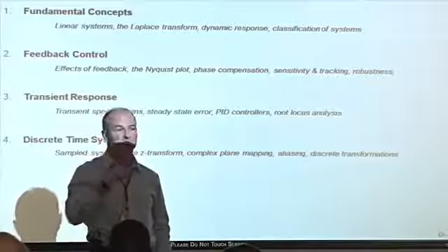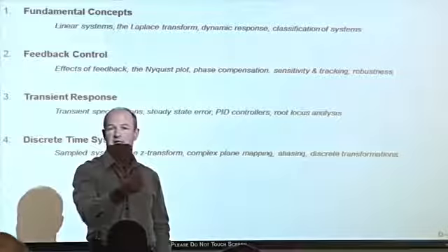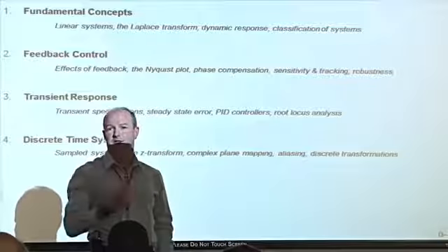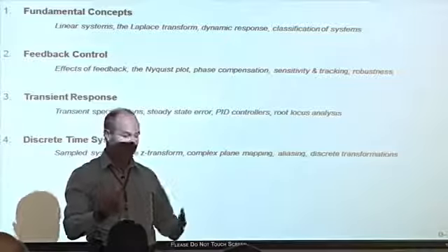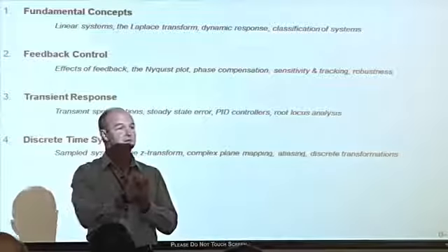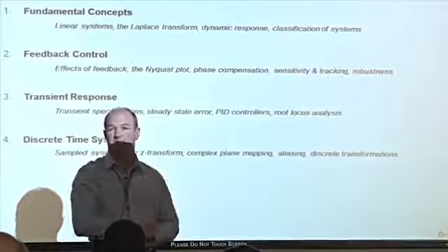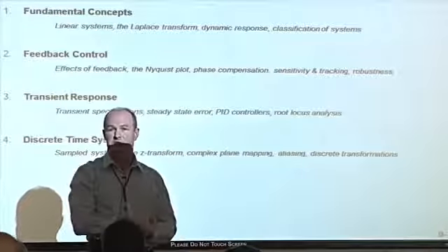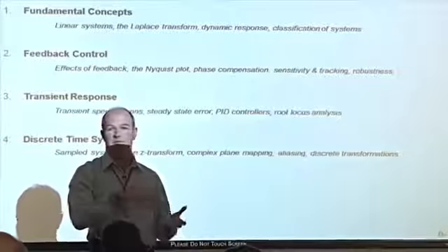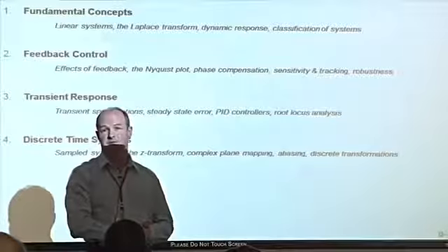You apply some kind of discontinuous input, such as a step, and then you analyze the output, the response to that. Now, the response, I'll show you shortly, comprises 2 different parts, one of which is the steady state part, and the other is called the transient part. The transient part for a stable system will decay, it'll die away. But the properties of the transient part capture the dynamics of the system. So by tuning those properties, we're tuning the performance of the system.